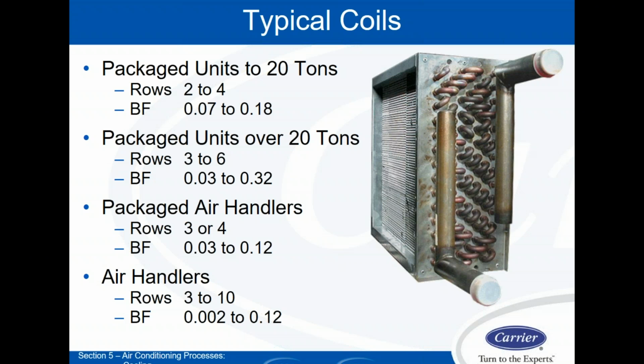And the amount of flexibility we get depends on what kind of commercial unit we're dealing with. If we have a packaged rooftop unit, especially smaller tonnage ones, we don't have a lot of flexibility. We're basically in the same boat as residential. You've got a couple choices, not a lot to work with there. But when you go into the air handlers, the semi-custom and certainly the custom air handlers, then you can pick the coil exactly that you want.